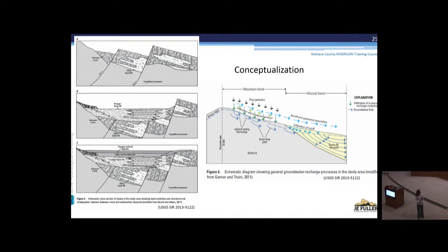Basement rocks. Basically, for hydrogeologists, a lot of times basement means that's the bottom of the world. We don't care anything about that. Sometimes there is still water in this basement area if it's very highly fractured. Sometimes it's not economical to go that far with a well because you drill way, way down, it's difficult drilling, and then you only get what's stored in the fractures, and that may not be very much. So most often, people will try to stick with the alluvium as long as possible. And once you tap that out, then you may have to start going deeper.